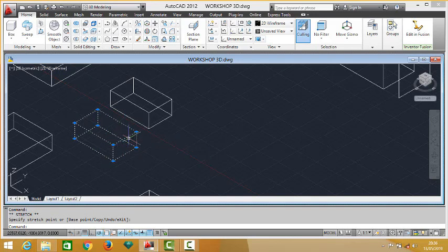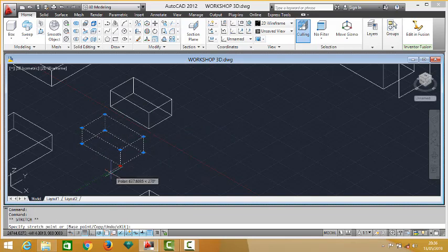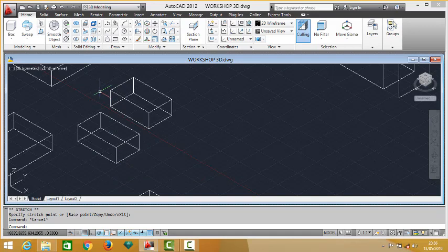That is to say, we can bring out this edge while the original one is still remaining here. Look at what is happening now. When you do this, all you get is the three-dimensional solid going along with you. But when you now come to extract edges and select it, it asks you to select object. Select this object and then tap enter. Watch what will happen now.